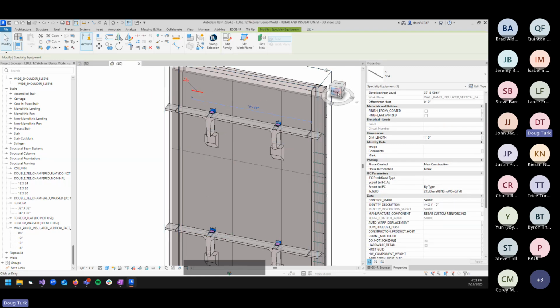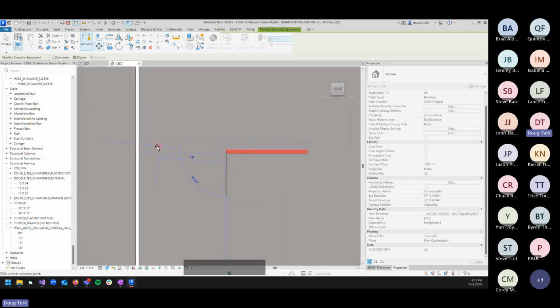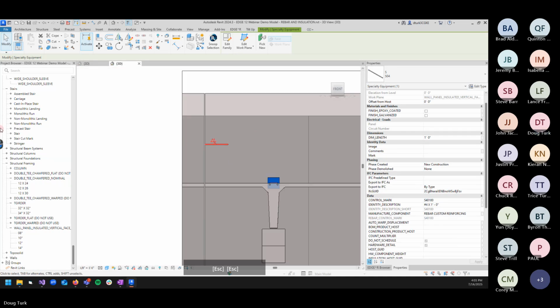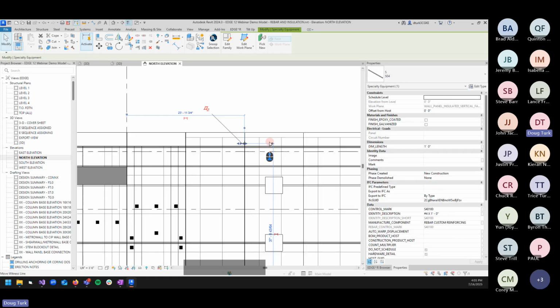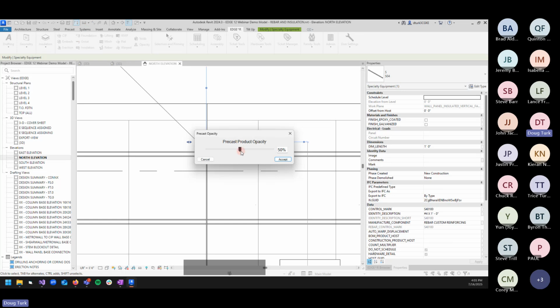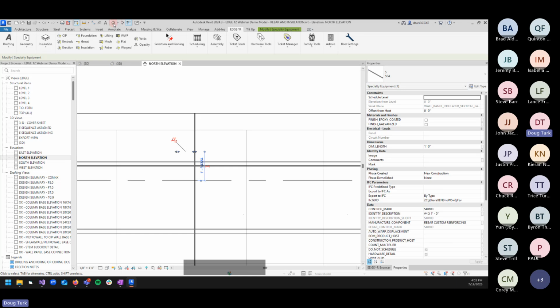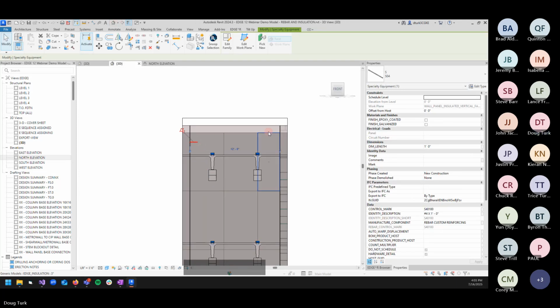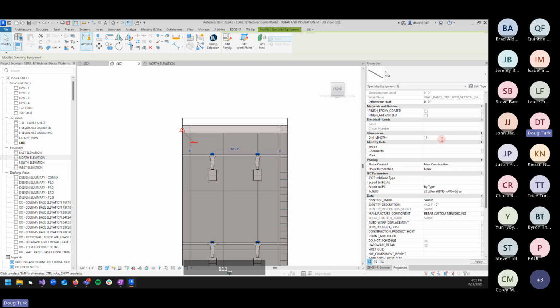But right now, our rebar is also a loadable family. Much like I mentioned with the products that we do, we don't necessarily use the Revit implementation of rebar. There are some limitations to that that we just weren't comfortable with accepting, especially when it comes to rebar marking and piece or bar by bar attributes. Revit really wants you to do certain things and treat the bars as groups, whereas we prefer to handle them as individual entities. So that's why we went with that approach.